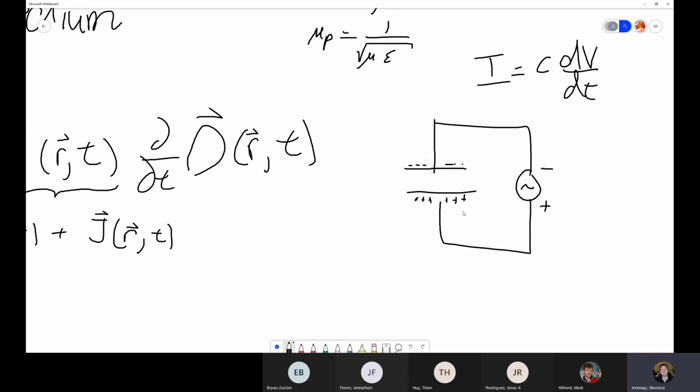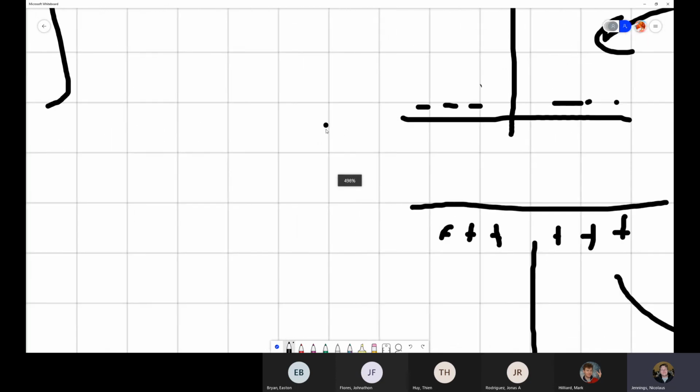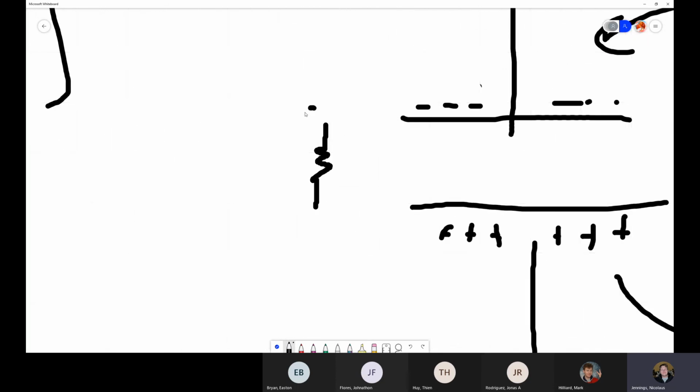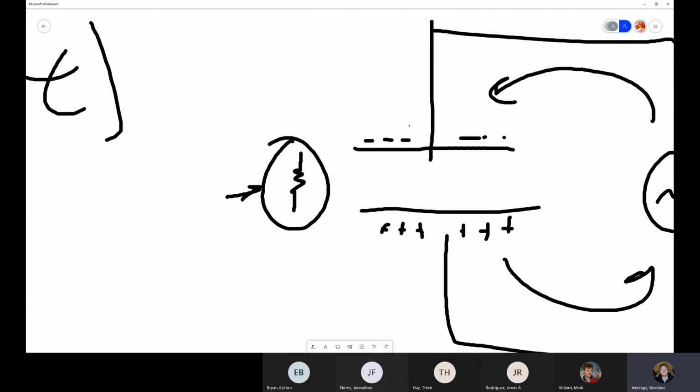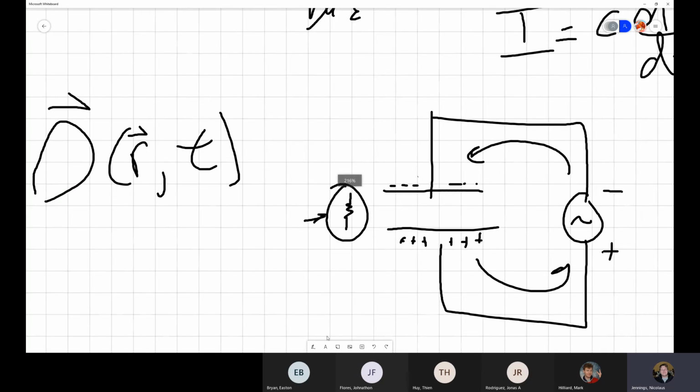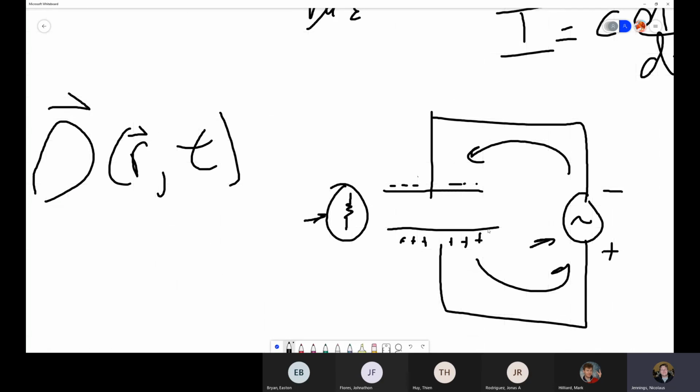So it's just the currents moving in this direction. They're going back and forth. They're not going through the capacitor at all. The current that goes through the capacitor is the conduction current, which is caused by the conduction of the medium. And so that's basically just the resistance. Displacement current only appears if you have a changing voltage, which is why I drew the sinusoidal source. If you have just a battery, the best you're going to get is conduction current.